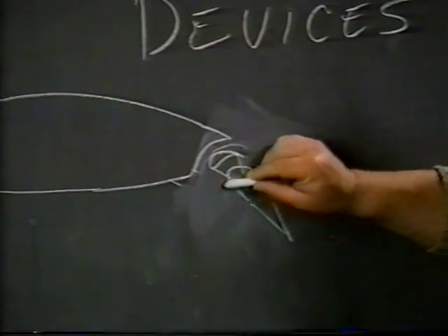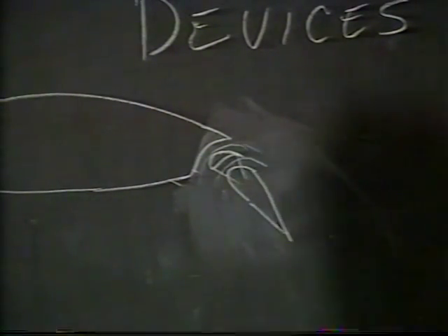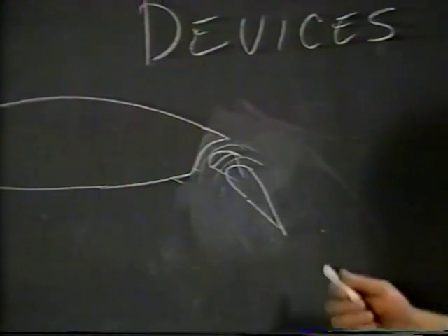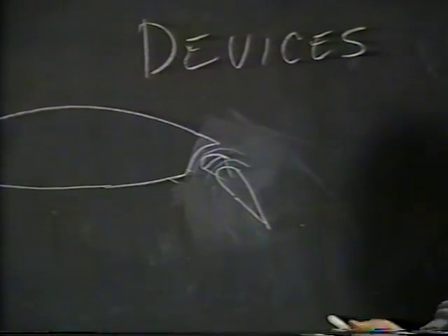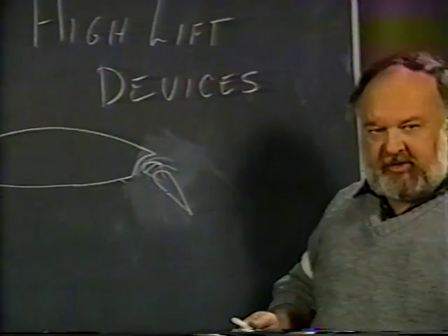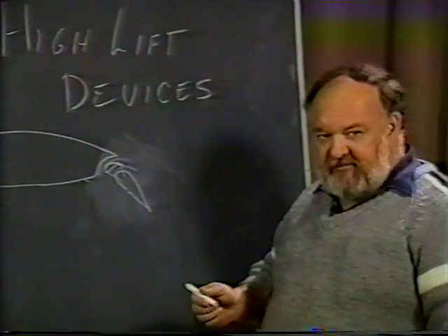You have one slot here and a second slot here, and that's, of course, where it gets its name, double-slotted flaps. This is a very effective flap, probably the most effective flap, based upon the total area, but it is complicated to make, rarely seen on general aviation airplanes, but very, very common on commercial airliners or military-type fighter aircraft or something like this.